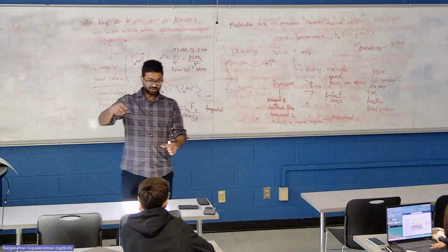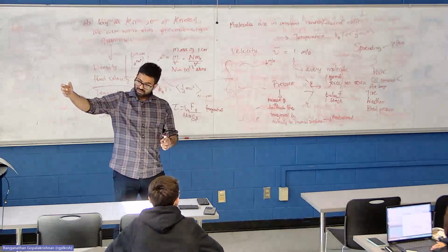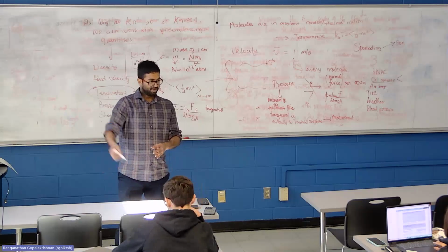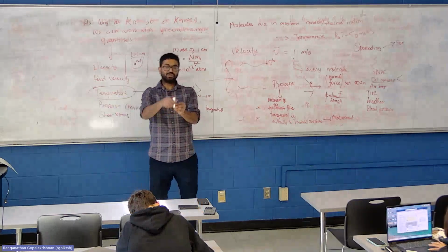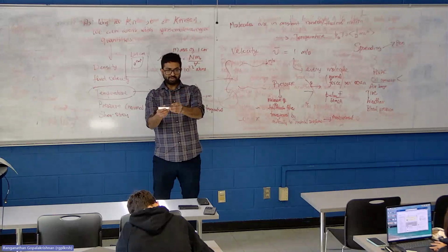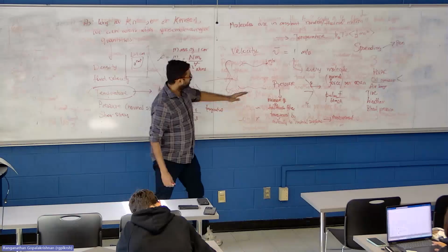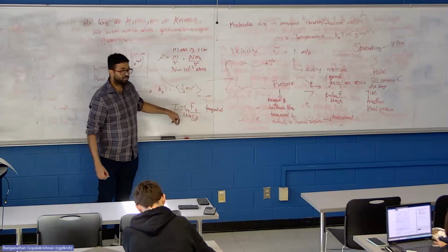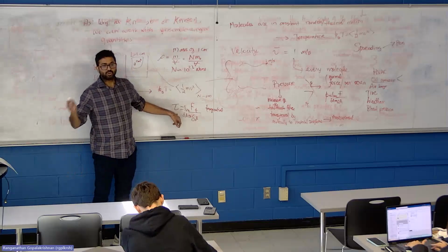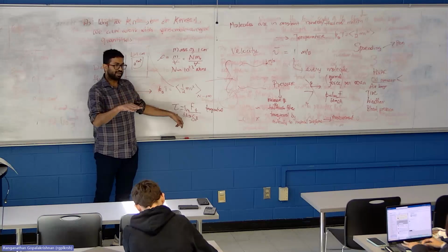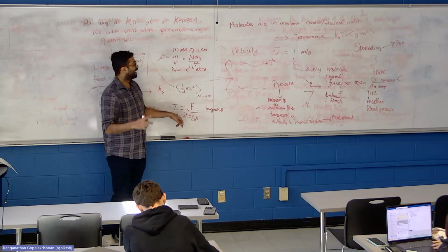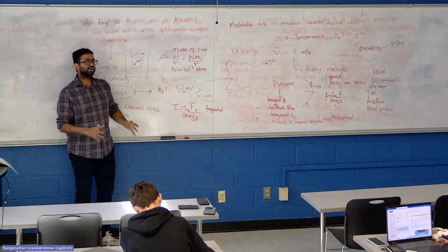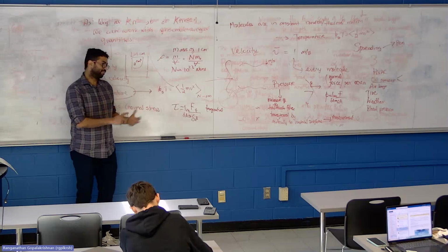That is what manifests as pressure, the normal force. But when the same ball, instead of being dropped vertically, hits the floor at an angle, you can resolve this motion into a vertical component and a tangential, or horizontal, component. The vertical component contributes to your pressure, the compressive normal stress. The tangential motion of the molecules contributes to shear stress. So there is no more magic left at the molecular scale. It's just their motion, but that manifests as temperature, velocity, pressure, and shear stress. It's the same thing, only we give it different names to denote different aspects of molecular motion.